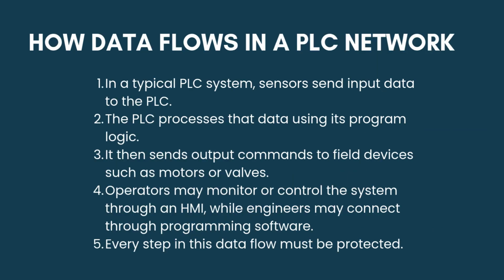To see why that matters, let's walk through how data moves in a PLC network. In a typical PLC system, sensors send input data to the PLC. The PLC processes that data using its program logic and then sends output commands to field devices, such as motors or valves. Operators may monitor or control the system through an HMI, while engineers may connect through programming software. Every step in this data flow must be protected because each step represents a possible point of attack or interference.